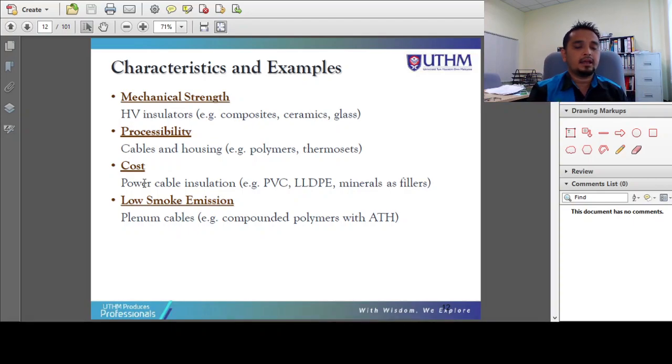These two materials can possess the same dielectric characteristic, but when we talk about cost implications, SF6 will cause huge financial implications, because you need to pay for this gas, and after a certain period of time the gas will be disposed of, and to avoid the environmental effect, you will be charged again to dispose of the SF6 gas.